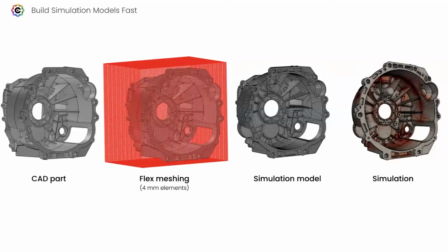And that simulation model is defined in terms of higher order smooth spline functions, which actually produces far superior numerical methods. So you've relaxed the constraints on meshing while producing methods that are superior to traditional FEA in terms of their accuracy per degree of freedom, as well as their robustness to large deformations, mesh distortion, all of those kinds of things that normally cause trouble in convergence, for example, in nonlinear problems.